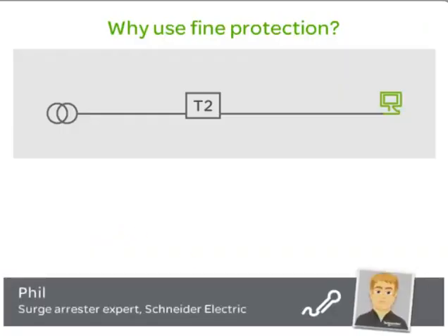Electrical installations in buildings are very widespread, and the cables may be several hundreds of meters long. In normal operation, the voltage is more or less the same at all points of the installation. When transient overvoltage occurs, the edge of the overvoltage spreads throughout the installation, creating wave reflection problems.